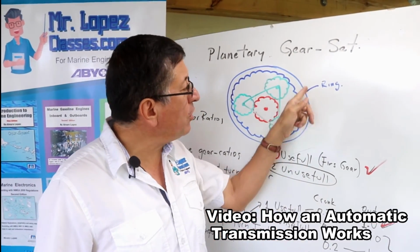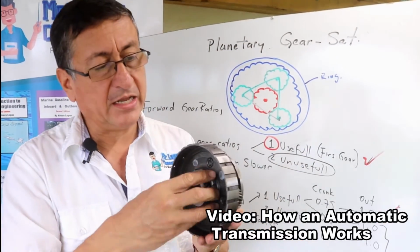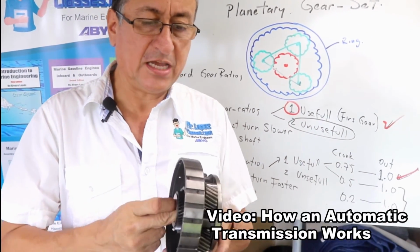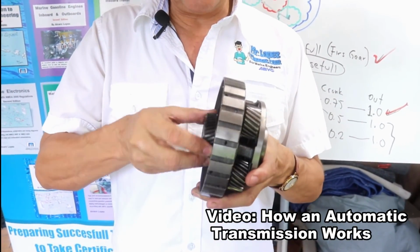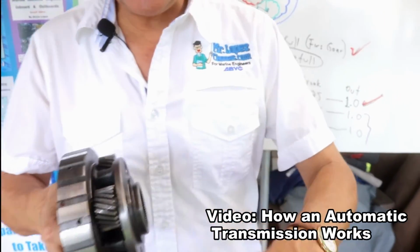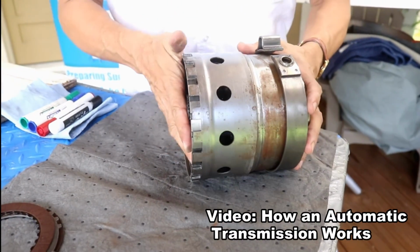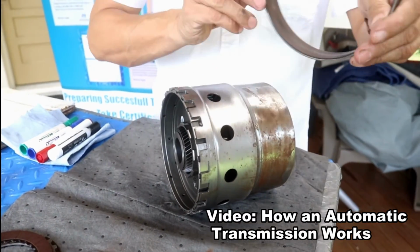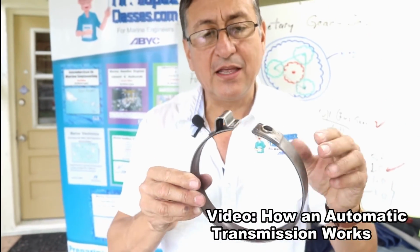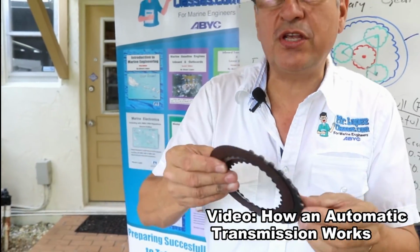For example, normally to stop the ring, this is the set of planetary gears. And in this set, the ring is here. This is the ring. The procedure to stop the ring is with the servo band. The servo band has friction material here, the same friction material used in the clutch pack.